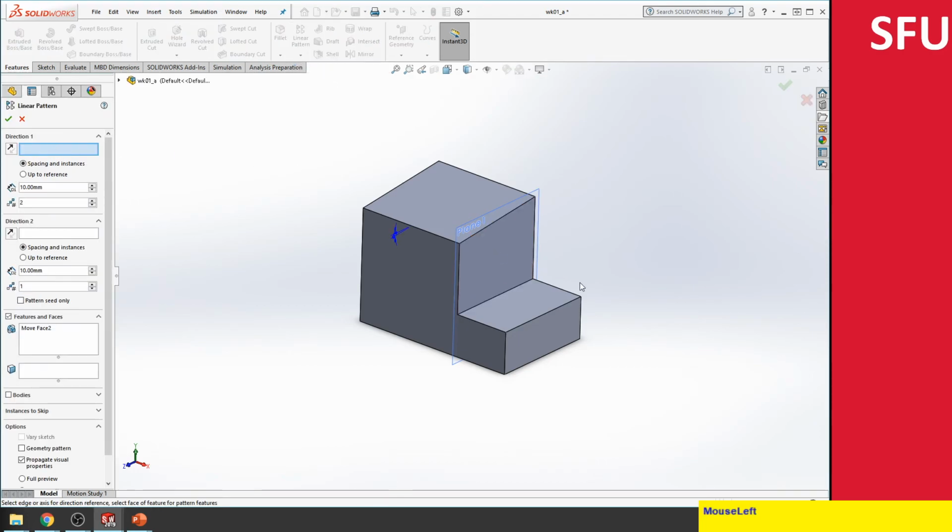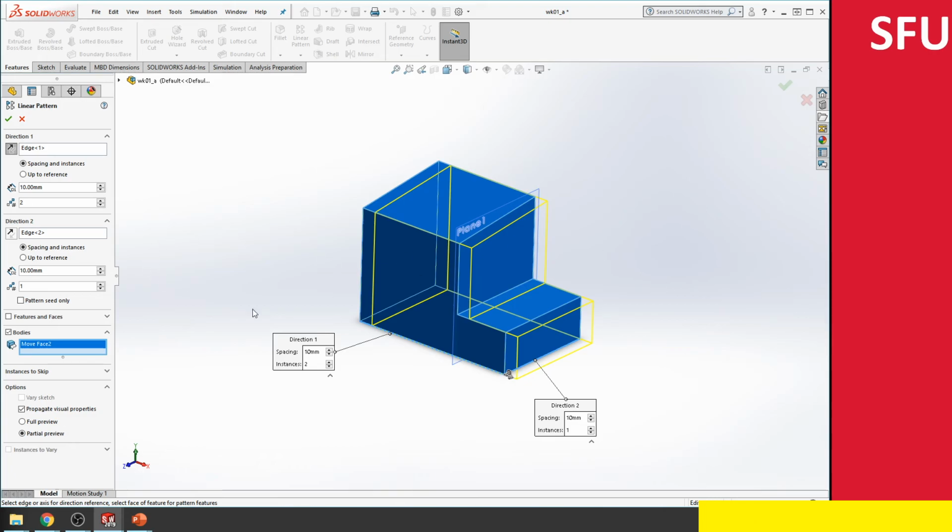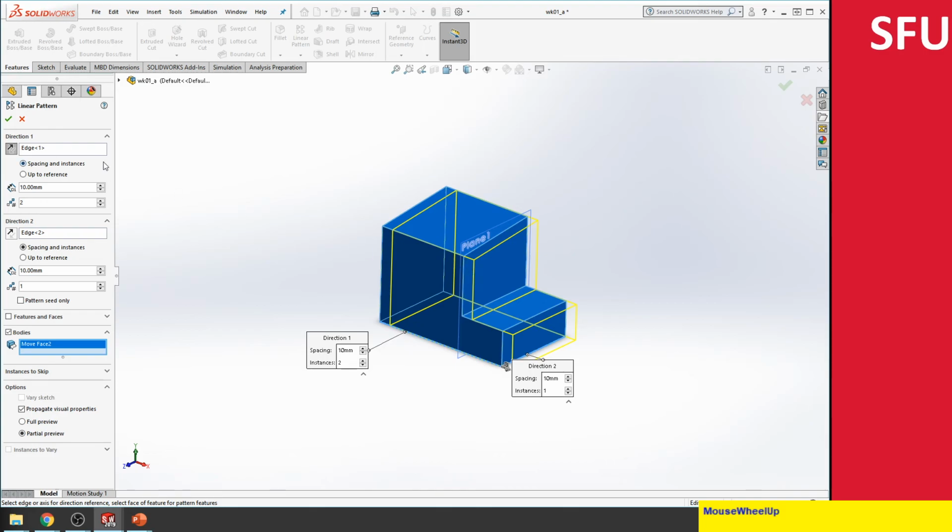So the first thing is asking for a direction 1. I'm just going to use these lines here. I'm going to assume this is direction 1, direction 2 maybe along this direction, and then the body that I want to select, maybe just this guy. So I'm going to select all of this, and it asks how far I want to move it. Maybe I want to move it by about 100.